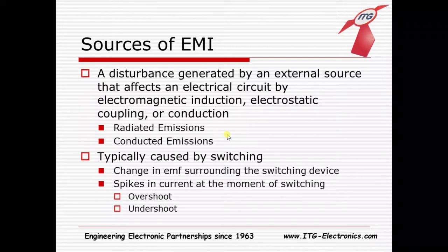And anything that doesn't match that signal is going to create noise in some way. And so that noise can affect obviously the equipment that it's a part of, but also it can affect the equipment around it, and even very far away in the case of radiated emissions, or even conducted emissions connected to the same circuits within, say, a house or a building.